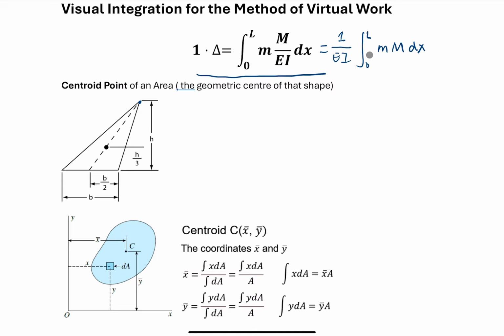But for some beam structures applied with a concentrated load or concentrated moment, we have to use multiple functions to express these two bending moments. Then we have to divide the beam into several segments and have several integrations, and we also have to come up with the expression for the bending moment as well. So this may take a long time.